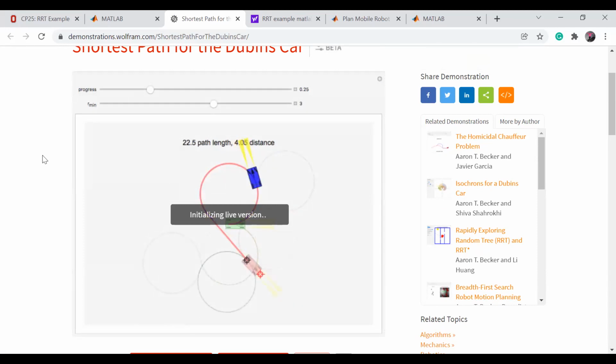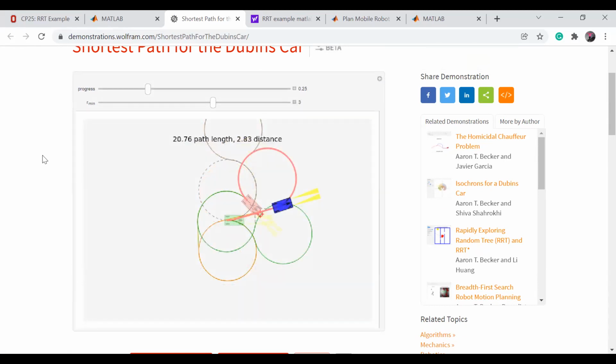So this is a whole different dynamic. It uses an underwater vehicle and an autonomous robot. Wherever you need to, you turn, go around an obstacle, go from one point to another. You can change plane, so you can move in 3D space. For my PhD project, the glider had to go down, turn, and the shortest path with the tightest circle was using Dubin dynamics. So the code for minimum turning radius is using Dubin. When you're reading the code, it says Dubin, and that's the idea.